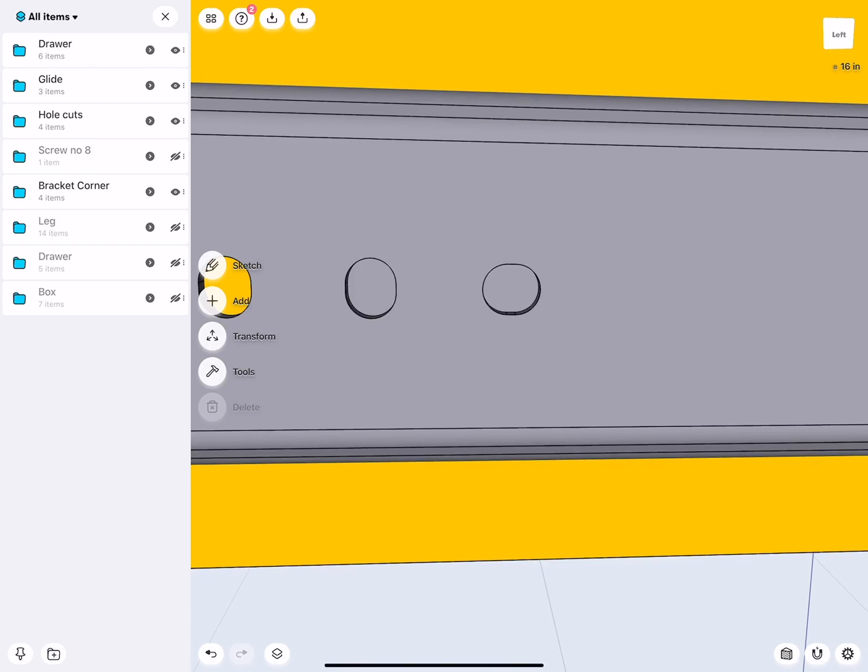The glide obviously needs to securely hold the drawer, but lumber might warp during the summer, winter, moisture, or the ground is a little bit uneven. Nothing in real life is as precise as in CAD, so you need to have ways to adjust these hardware parts, let's say like here glide, around pre-drilled holes.